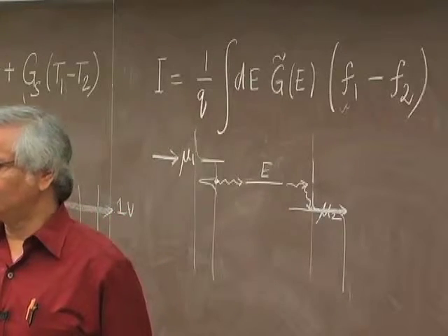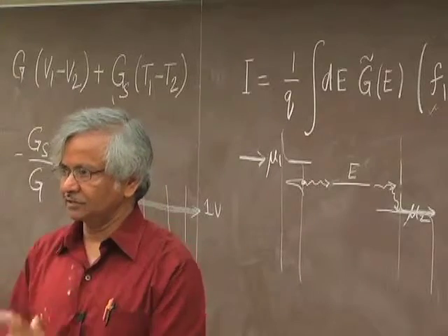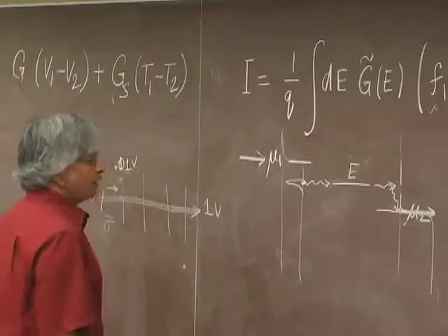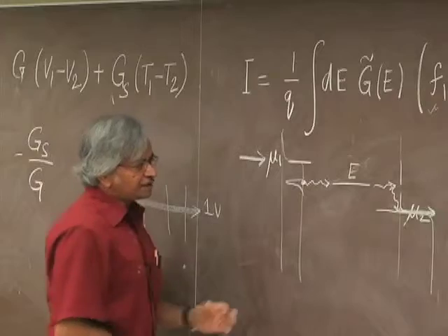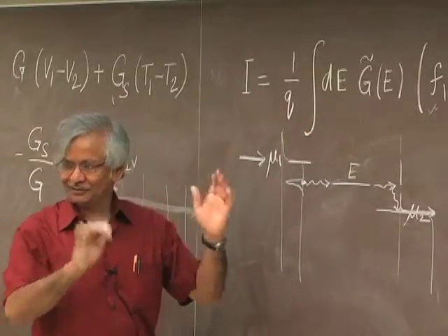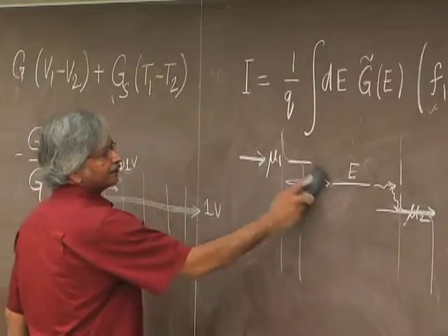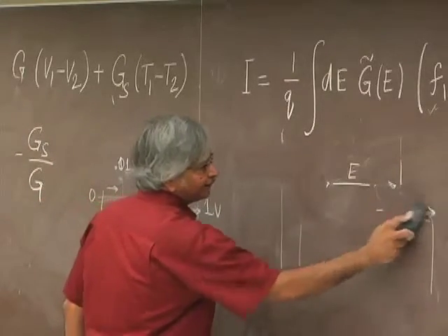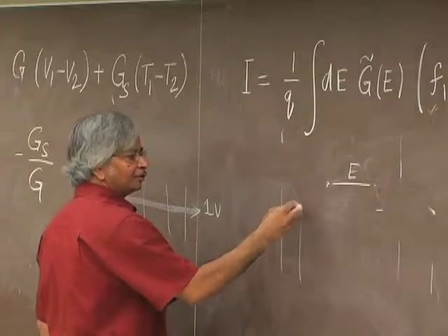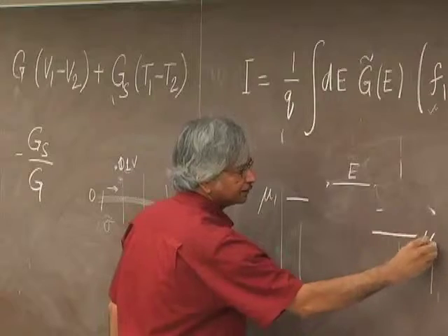That's the Joule heating. We know that a battery with a voltage V delivering current I, that's the heating. Okay? But in between, you'd say this. So this is how I explain the normal resistor, the elastic resistor, whereas the heating is. And what we are now saying is that in a thermoelectric, it's a little bit like the mu1 is here and the mu2 is here, let's say.